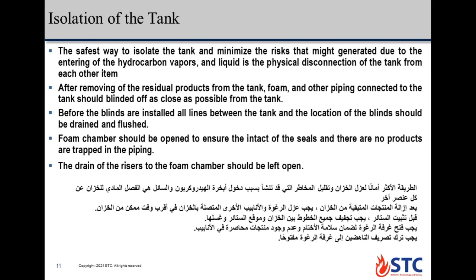After removing of the residual product from the tank, foam and other piping connected to the tank should be blinded off as close as possible to the tank.